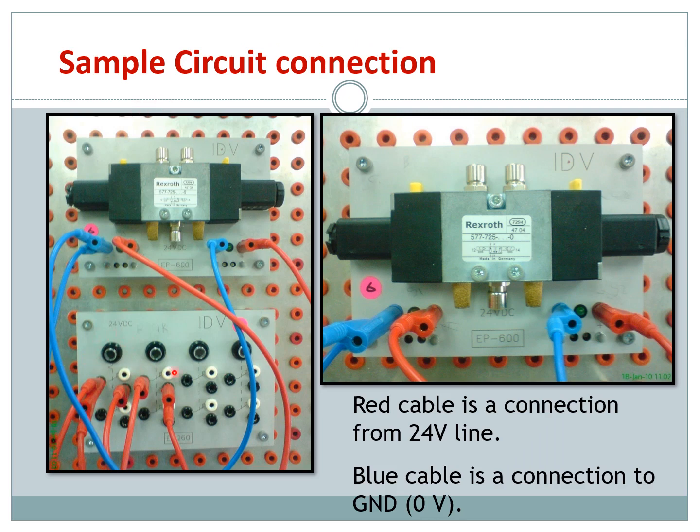So you can see you have four push buttons here. Okay, it's connected here. So you have 24 volts, and normally we use a red cable to show positive, or 24 volts, and we will use a blue cable to indicate ground. So we will have all the connections here. Based on this, it is similar to your pneumatic, so you will control your cylinders. Okay, but because of the inputs given from the electrical board, the solenoid will be activated. Okay, so similar here.